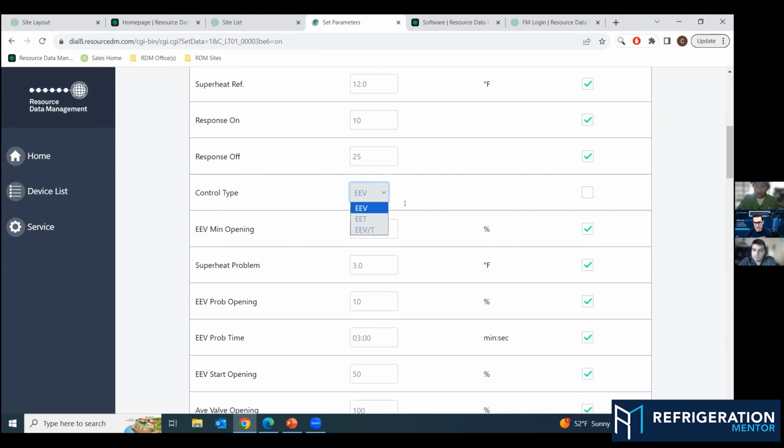Well, if your temperature in that case is reading 25 degrees or 30 or 50 degrees, it's going to make that valve wide open until it gets down to, it's basically a chart inside the controller is what I've kind of figured out, a rate of time versus change and so on and so forth. And until it gets in that bubble again, it's not going to revert back to superheat. It just won't. So you get floodback instances, and then you get frosting going on, and you just get a lot of things going on. So that's a real important setting on these case controllers.